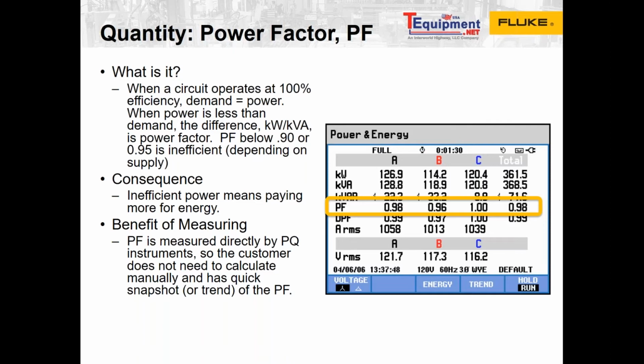If you're a larger energy user, the utility gives you a better rate on each kilowatt hour used, but only if your power factor stays above a certain point. It depends on where you live, but usually it's 0.95 or above, and you won't have to pay a penalty. The interesting thing about that is if you are below 0.95 in our example, even if it's only for a little while, you get charged for the entire billing period.